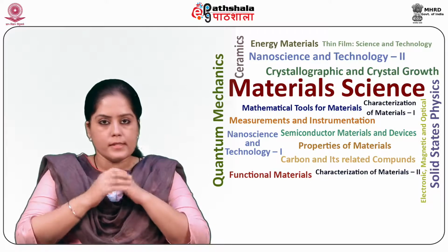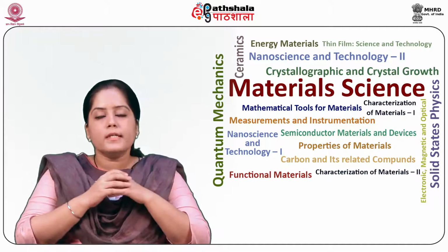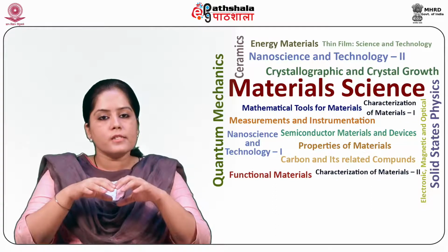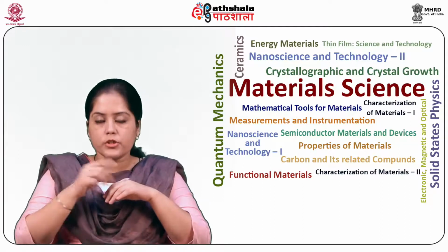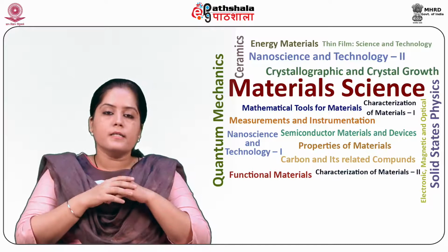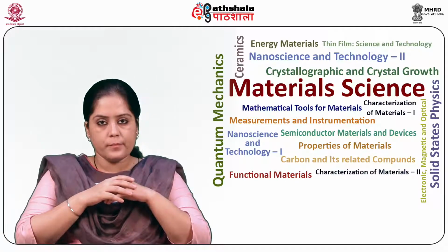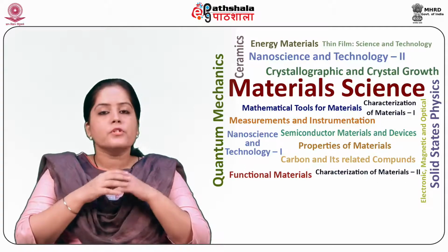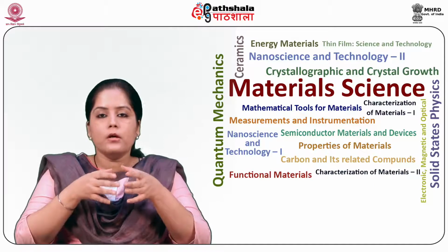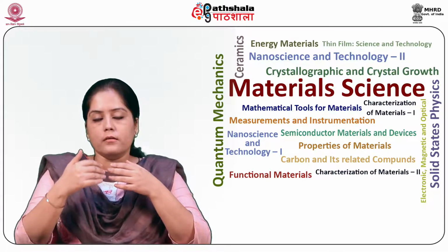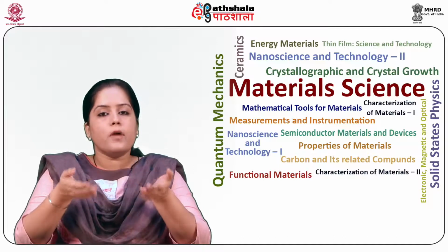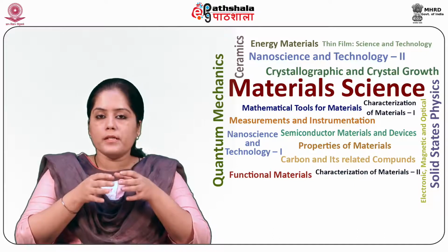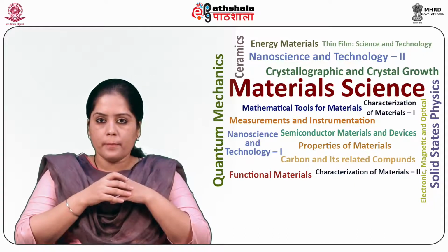production of devices. The possible techniques used for thin film deposition are broadly classified into physical vapor deposition process and second is chemical deposition process. Physical methods cover the deposition techniques which depend on the evaporation or the ejection of the material from the source, that is evaporation or sputtering, whereas chemical methods depend on chemical reactions.